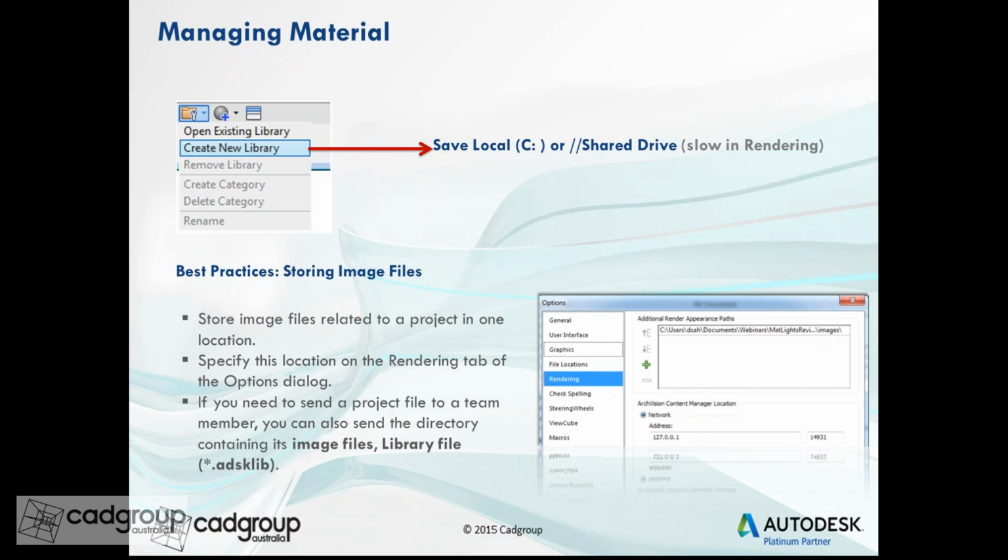If they transfer the project from one PC to another and render, some of the rendering doesn't come out with the proper material they assigned, which is obvious, as the custom images or materials that you apply are reference files and not saved with the project. I've highlighted some of the best practices for storing images within this slide.